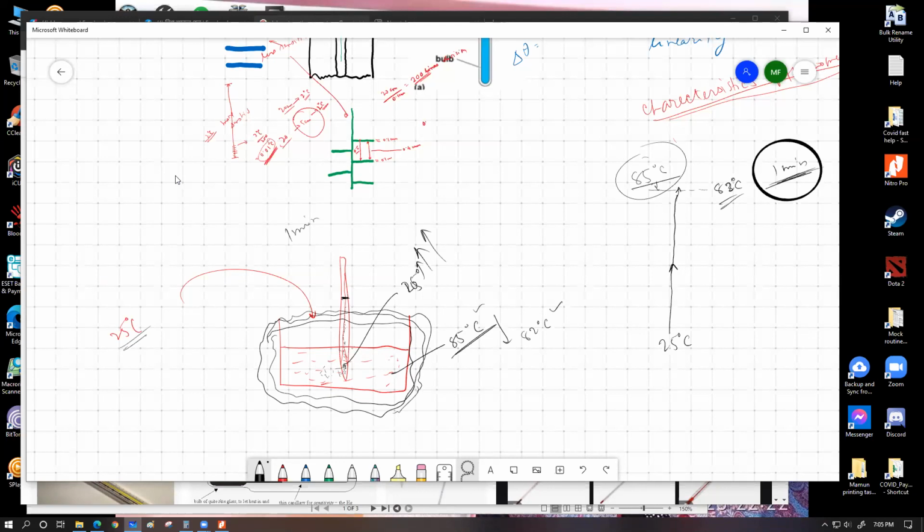This is true for all thermometers, because to give us a steady, true reading of the hot body, the temperature of the thermometer itself has to reach that temperature. The thermometer has to be heated up to the temperature, and only then there will be thermal equilibrium, and only then can we take the reading out of the thermometer. So for the temperature of the thermometer to rise from its original temperature to that high temperature value, it is always going to take some time.